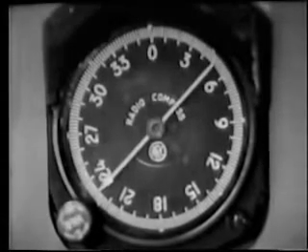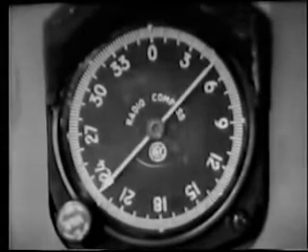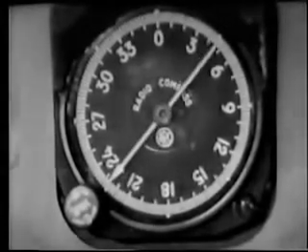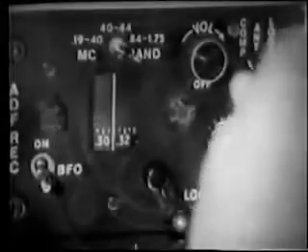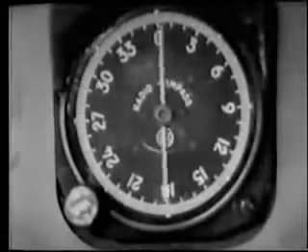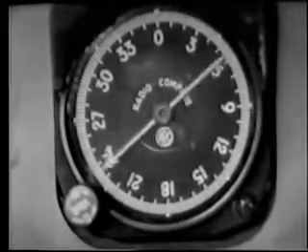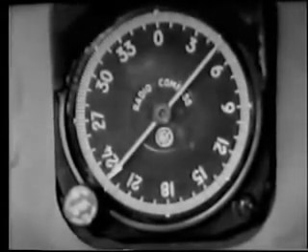For fine-tuning, we set the function switch to the compass position and tune for a maximum deflection of the tuning meter. Once this is done, we check the ADF indicator to see that it gives the appropriate reading for the station used for this check. Always check this reading by driving the loop away from this position with a loop drive switch to see if it will return automatically to the same position. That checks. A further check can be made by switching to the loop position to see if we get a null in this position. Okay, we're in business. Let's call for clearance and get started.